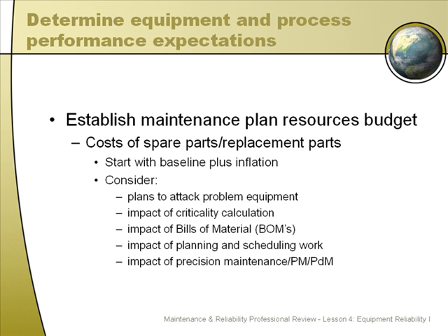After you have that, you can do a very nice report in most CMMS software, and actually most ERP software as well, to figure out where the parts are needed and where they're not. Let me give you an example. If you have done the criticality calculation on all of your equipment and you have a list of what's high criticality, what's medium criticality, and what's low criticality, and you have bills of materials for all of your spare parts, then you can run a list of spare parts that are stocked for low criticality equipment. This is a great place to start in reducing your storeroom inventory because these parts are probably not necessary if the criticality calculations are accurate. It's a really great place to start, and it's a fairly low risk situation to get rid of those parts.